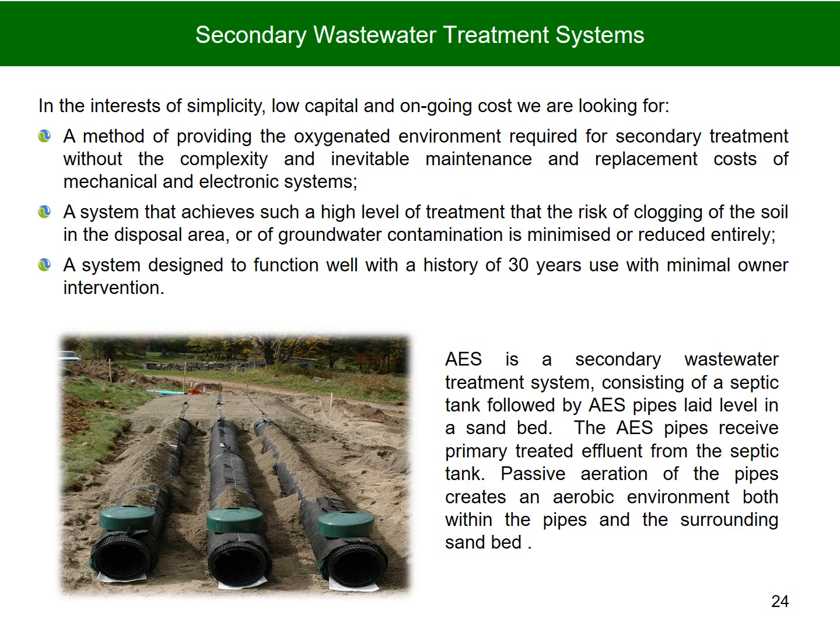The following slides deal more specifically with the AES system. AES is a secondary wastewater treatment system consisting of a septic tank, followed by AES pipes laid level in a sand bed. The AES pipes receive primary treated effluent from the septic tank. Passive aeration of the pipes creates an aerobic environment both within the pipes and the surrounding sand bed.